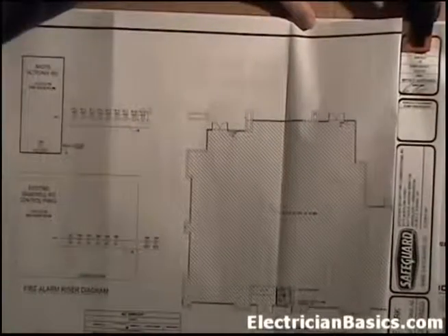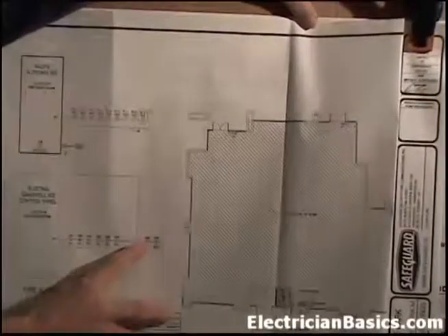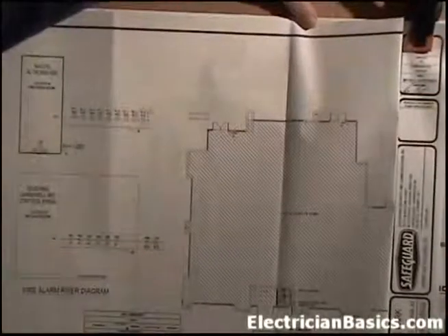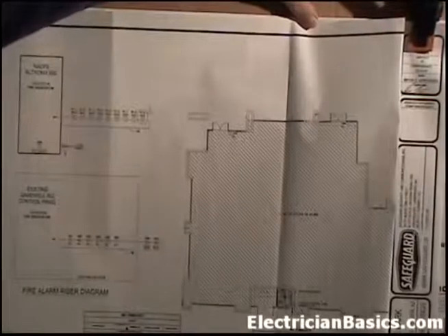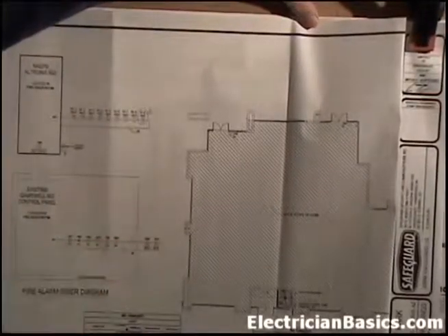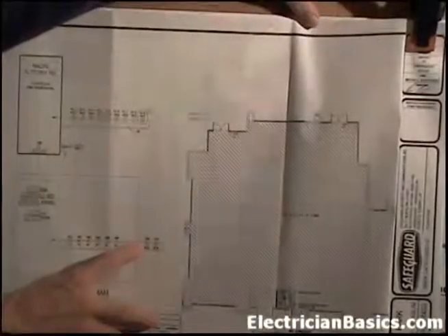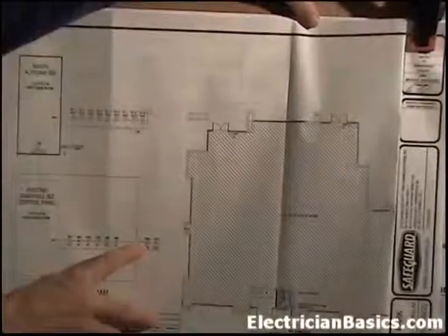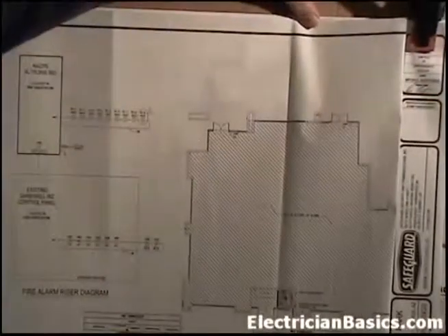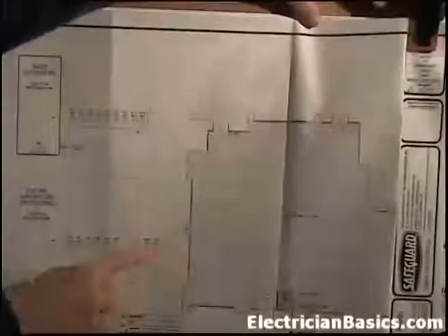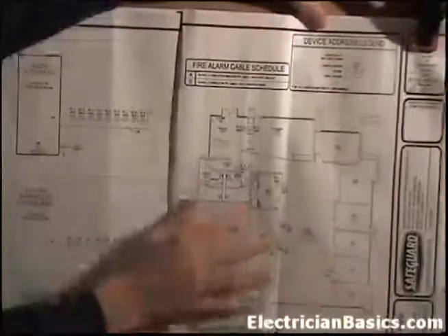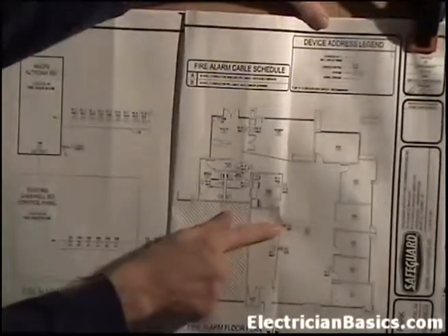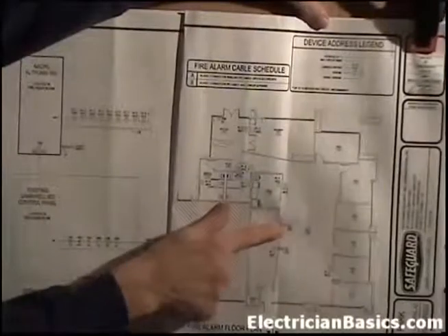Okay, now that we've covered that, let's look here. Remember we have a S by the line. That's a broken line, which means a break in the conduit, but this still runs together and loops together. We have here smoke fire damper. That's what SFD stands for, and the M stands for addressable monitor module. And we have 1010, same thing. Now if we go over here, we have 1010M and 1009M, addressable monitor module.